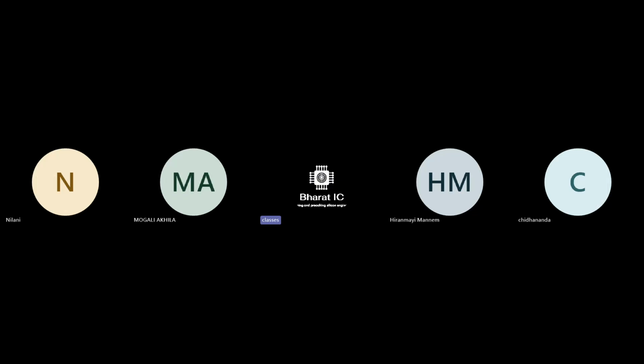Okay, so up till the N implant we completed, right? Or no? I think the N-well masks. I think we have progressed up till a much level. PMOS fabrication we did, NMOS fabrication and annealing we did, contact cuts we did also. And the metallization, metal 1 and metal 2, both we did actually. We completed up till that; we were left to do the overglass and pad opening things.